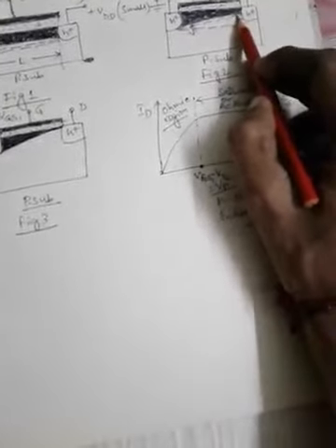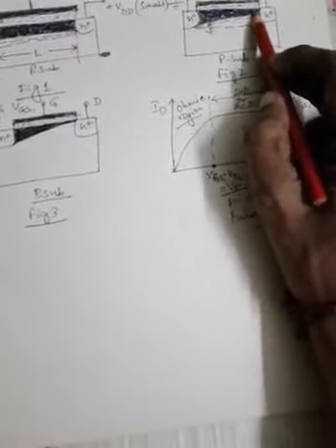So you can see initially it was uniform, horizontal. Now the width of the depletion layer at this region near the source is far less than near the drain. So in this area the width of the depletion layer is far more than in the source area. So what does it mean? The width of the depletion layer is pushing the channel width to a reduced value. So what does it mean? As a result of the increase of depletion layer width, the channel width is reduced.